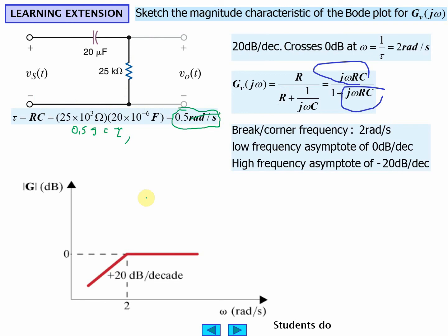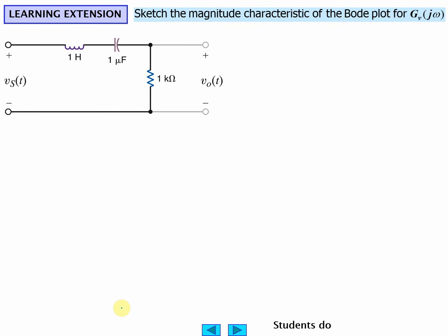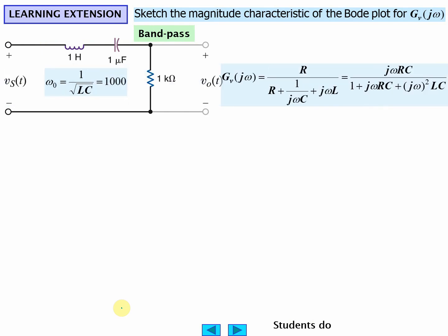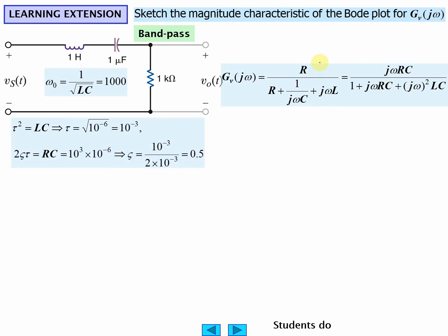So we can draw the Bode plot this way. Remember it was a high-pass filter. So it's going to look like this, and just finding this is the key point. Asymptotic behavior. Okay. Now we have an LRC filter. It's going to be a band pass. We're going to get the gain is the resistance over the impedance. And we go figure out all our parameters.